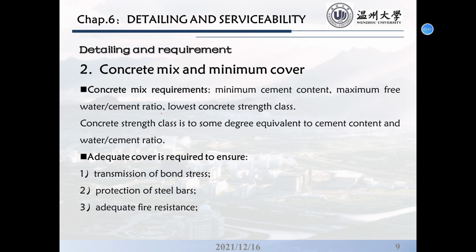An important ratio is the water-cement ratio, which will affect the flow of the concrete. If there is more water, the concrete flows smoothly, but if there is little water, it is hard to work. We also need to realize that different ratios of these ingredients will affect the concrete strength.